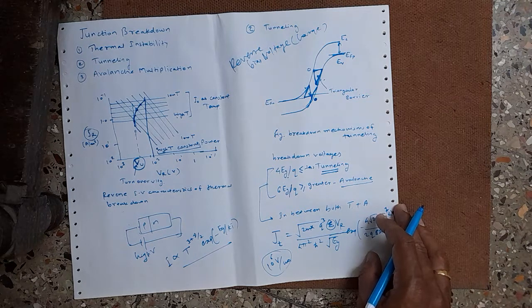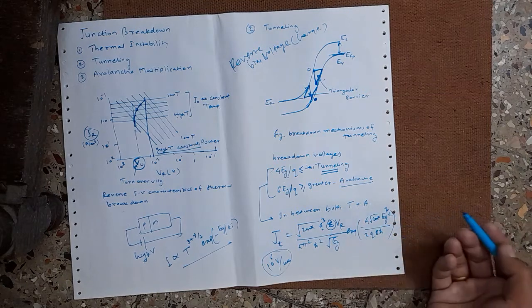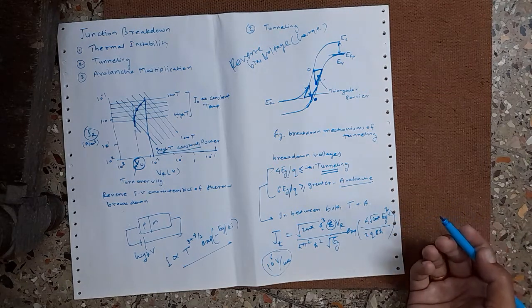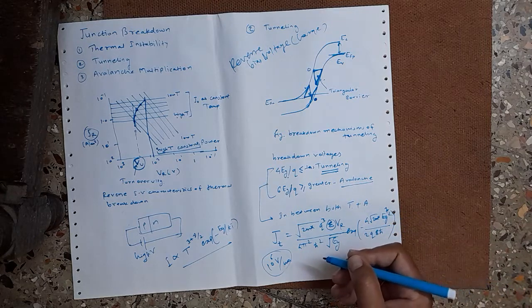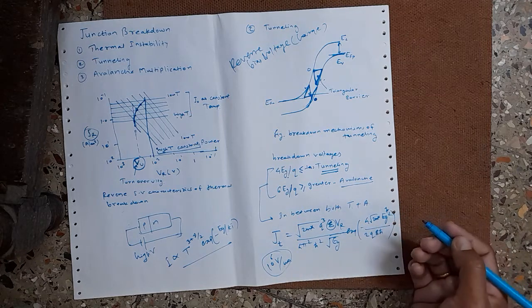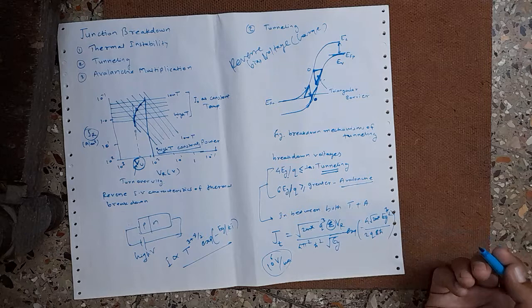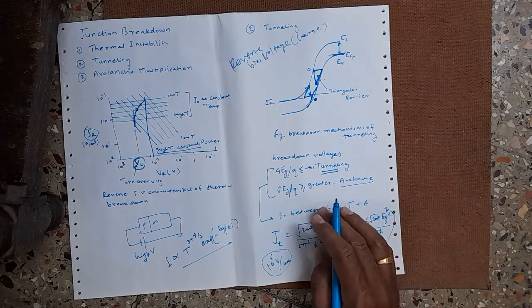That is, breakdown voltage decreases with increasing temperature, because a given breakdown current can be reached at smaller reverse voltages at high temperature. The temperature effect is generally used to distinguish the tunneling mechanism from the avalanche mechanism, which has a positive temperature coefficient, that is, breakdown voltage increases with increasing temperature.